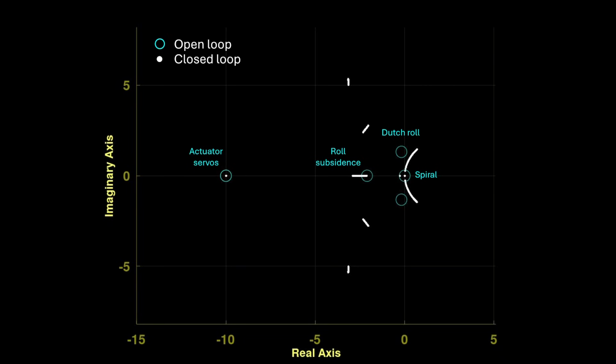Note, there are more closed-loop eigenvalues in white than open-loop eigenvalues in blue, due to the presence of two integrators and a washout filter in the controller. It can be tricky to trace closed-loop eigenvalues to their processes. This is because, in the limit of low control effort, while closed-loop eigenvalues approach open-loop eigenvalues, here we have an existing tuned beta dot inner loop controller.